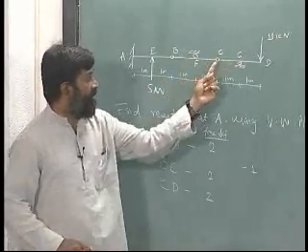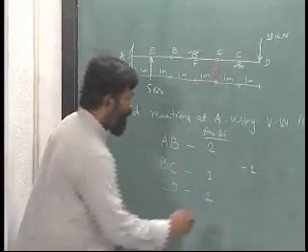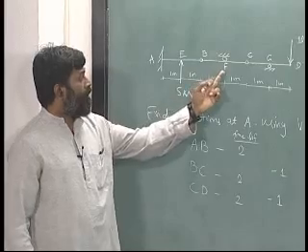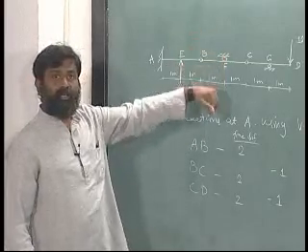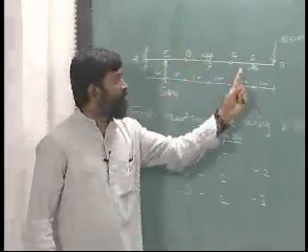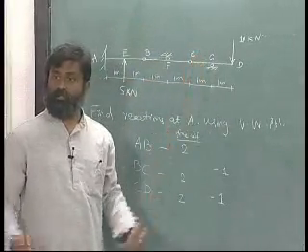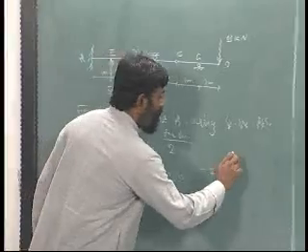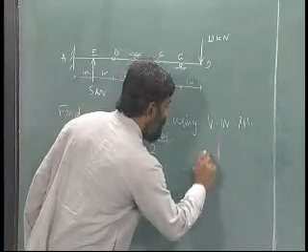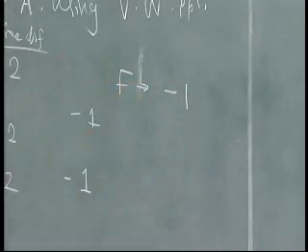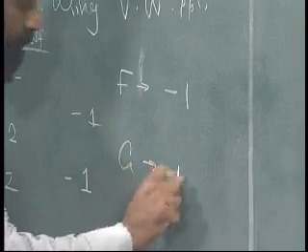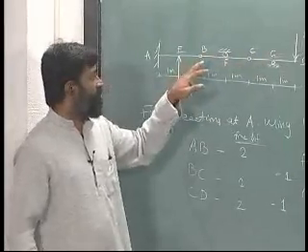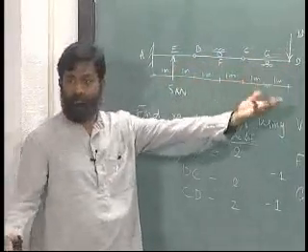Between BC and CD, another constraint is in the form of hinges there. So, one more is gone, alright. How about the support at F? It vertically constrains the motion. Support at G again vertically constrains the motion, which means one constraint each at F and G, right. So, F offers -1, G offers -1, alright. So, we have considered F, we have considered C, we have considered B, we have considered G, D is free.